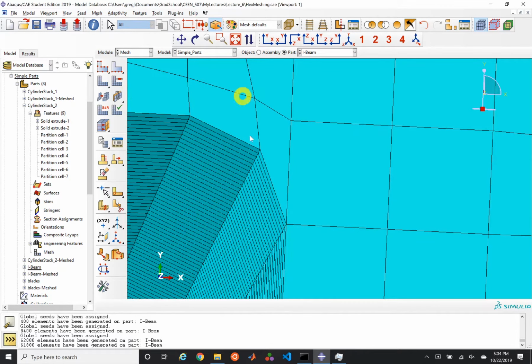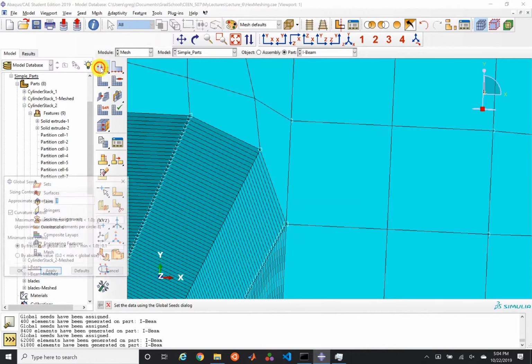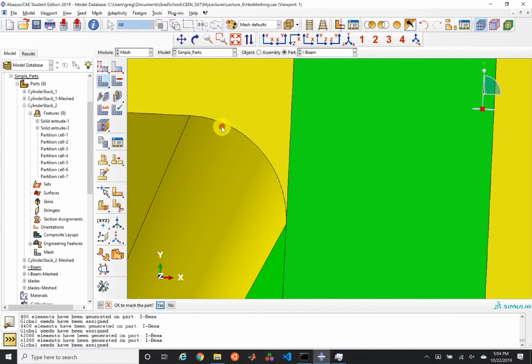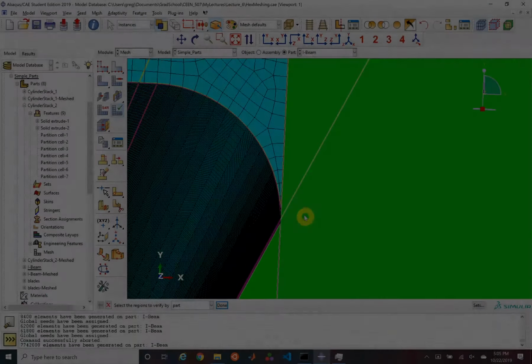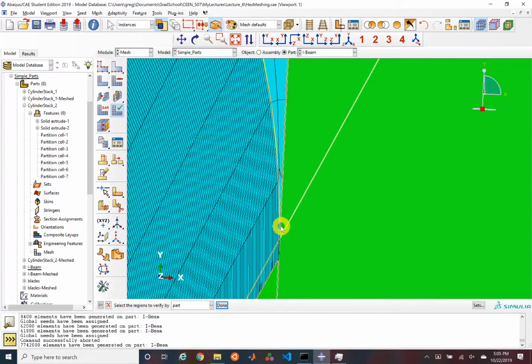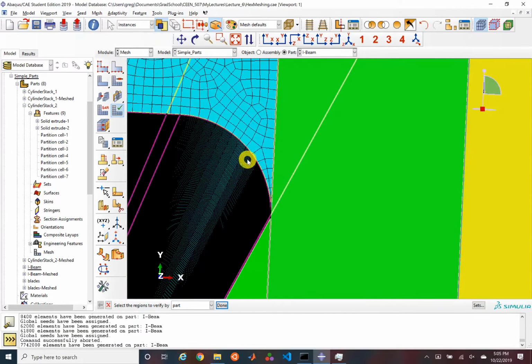And if this thing is tangent, as we increase our mesh density, say 0.1, it's going to take a little bit. You can just see these hex elements continue to come flying in here and get really small and really bad quality.